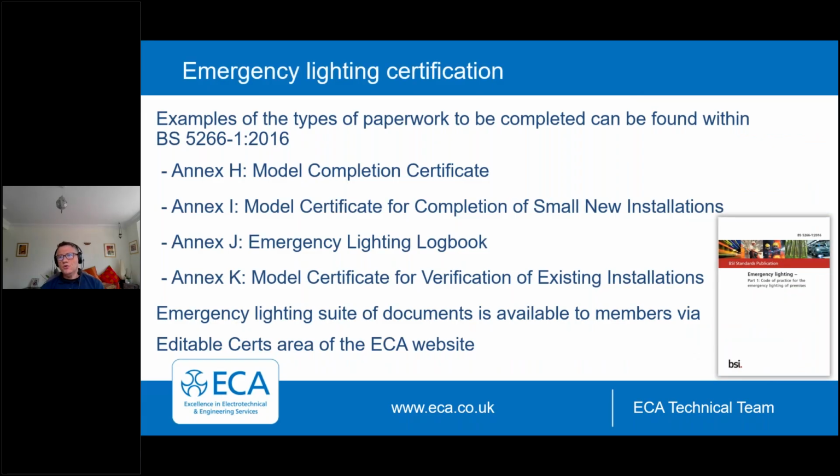But with regard to certification, thankfully and rather handily, there are lots of different types and examples of that given in the annex of 5266, and it covers most eventualities. We've got the completion cert for small installations, larger installations, and it gives us an example of an emergency lighting logbook and how to verify existing installations. And just a little reminder at the bottom there, the emergency lighting suite of documents is available. We do have our own editable certs on the ECA website.